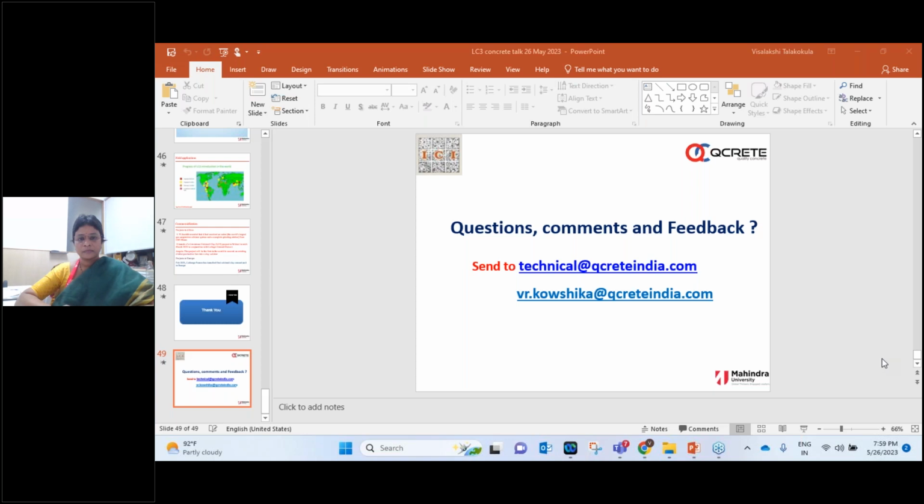Thank you, ma'am. The next question is, difference of setting of concrete in comparison with Portland cement and LC3, initial and final setting time of concrete, asked by Razi. Initial and final setting time of this LC3 concrete. LC3 concrete has, what you say, delayed setting, which we have observed in our lab compared to that of a Portland cement concrete. It had got a delayed setting.